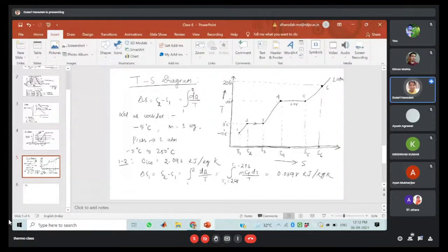So that solid to liquid conversion will be achieved by the latent heat of fusion, right? The energy that is being absorbed is the latent heat of fusion, right? That energy is utilized and your phase change happens. So that temperature is 0 degree Celsius and that pressure is 1 atmosphere pressure.